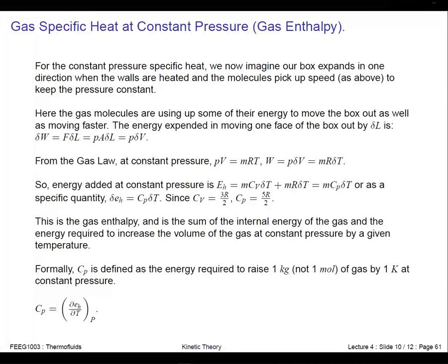Okay? And you can work out how much work this gas is doing when it's being heated, because if you have a small element of work, this is the force on the piston from the gas, and the piston moves a small amount, and that force that's created by the pressure in the gas is the pressure times the area of the piston, and that gives you the pressure times, if you like, the change in volume of the gas. Okay?